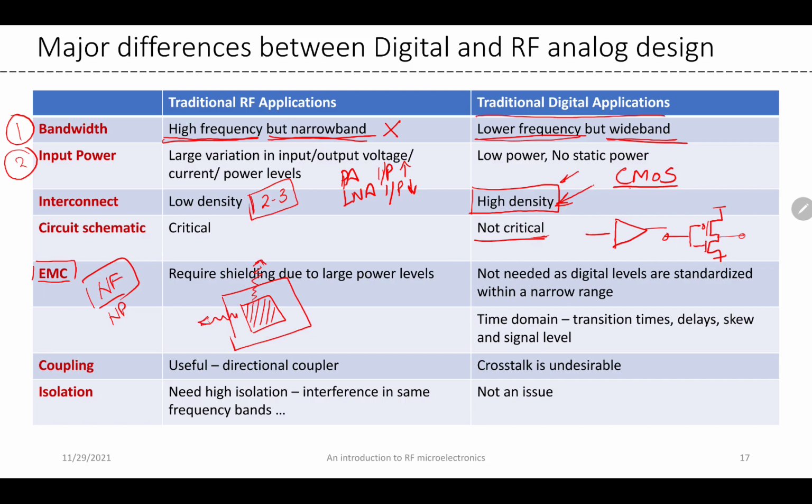If you're working with high powers and high frequencies, you have to make sure you have proper shielding, so that the device does not leak radiation and start interfering with other products in a similar frequency band. This problem only emerges at high frequencies, because it is only at high frequencies that you start seeing radiation.